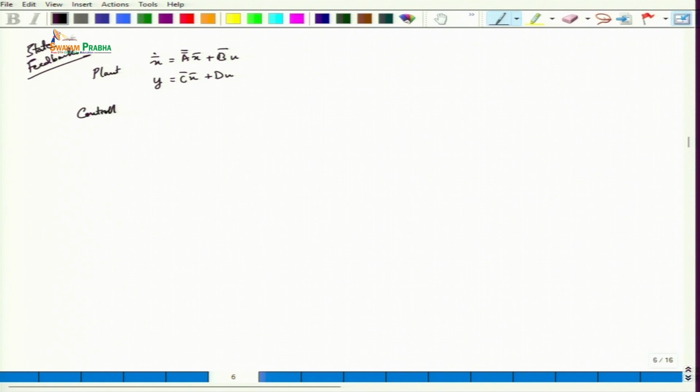And the controller here, I believe it's quite obvious from the name when we say state feedback. It's U equals minus K times the state, where K is the gains of the controller, which as control designers we are going to formulate. We are going to discuss how we find that now. But basically it's U equals minus Kx. So we are taking feedback from the states and multiplying by gains and formulating it into the control input.